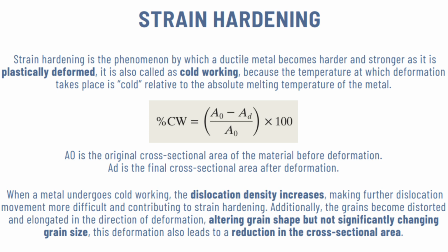melting point of the metal. So we can actually calculate the percentage of cold working that has been done to a material by a rather basic percentage formula, which is percent cold working equals the original area minus the area after deformation, over the original area, times 100%.